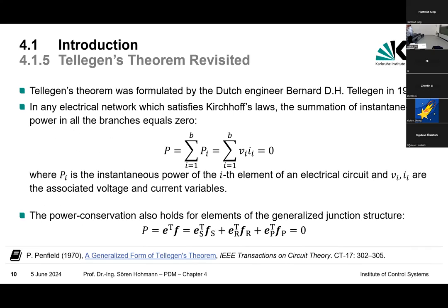For some of you, or for others, it's new. But the interesting fact Tellegen found out, it's really old, is that if you take a network, an electrical network, you can do this at home. It's a good stop point for today. You take an electrical network and you calculate the power of every branch. You sum it up, but you will find out that it sums to zero. Because some of the currents go in opposite directions, and therefore you get always zero.